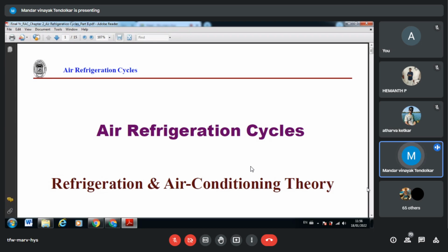So I will say compressor efficiency, let's say 90%, or volumetric efficiency 94%. Accordingly, your final enthalpy values would change. You can calculate m cp delta T as the theoretical one. And then you have to consider the turbine efficiency: volumetric efficiency for the compressor, adiabatic efficiency for the turbine, basically the polytropic one, and something like that. Okay, so this is just how to apply the basic theory.